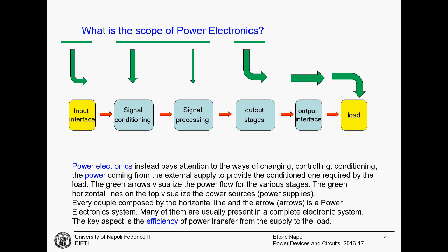This is a problem not only for the power dissipation, for the cost of the energy, let's say the amount of the bill that you have to pay for this extra energy. The real problem is also the heating. When you dissipate this amount of energy, your circuits will become hot and the reliability is destroyed.